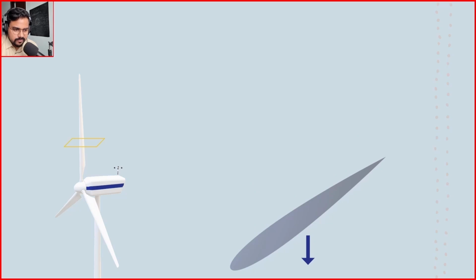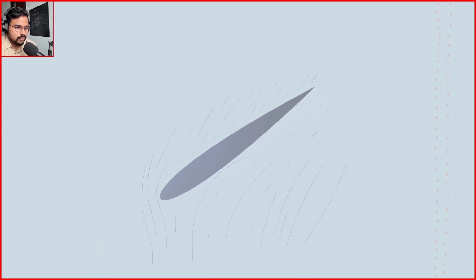And as the blades are moving, the blade that we have, the airfoil right here, is also going to move in a particular direction. Now, it's necessary for us to understand that the oncoming air is flowing through these wind turbine blades, and that is causing the turbines to move inherently. Now, as they are moving, the flow profile that gets created looks more or less like this. There are regions here where we can see that fluid is not exactly following the entire contour of my particular airfoil shape. Again, it is separating away from my blade due to how it is oriented, and at the same time due to pressure differences as well.